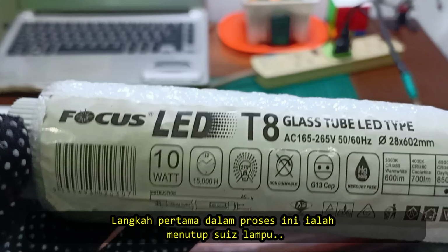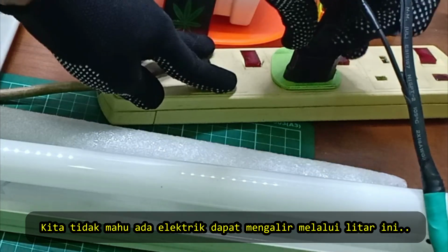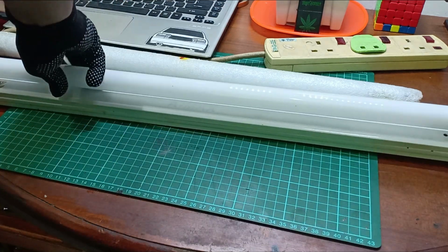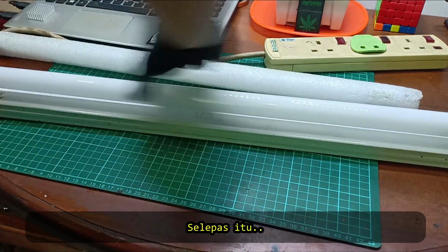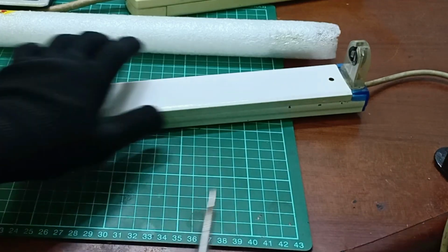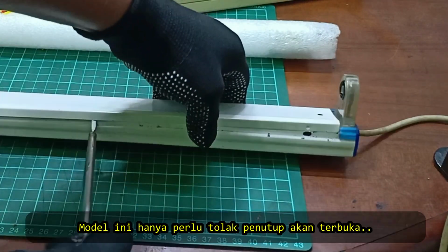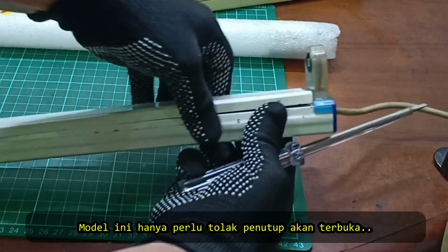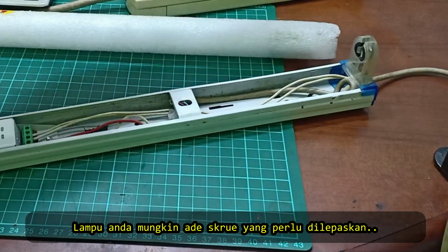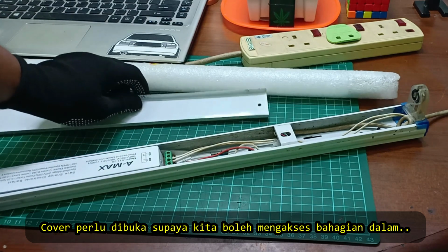The first step in this process is to disconnect the power. We don't want any electricity to be able to flow through this circuit while we are doing this. After that, you will want to remove the existing fluorescent tubes. And then remove the cover. This particular one, you just push the cover up to be removed. Yours might have screws that need to be removed. We need to remove the cover so we can access the wiring.